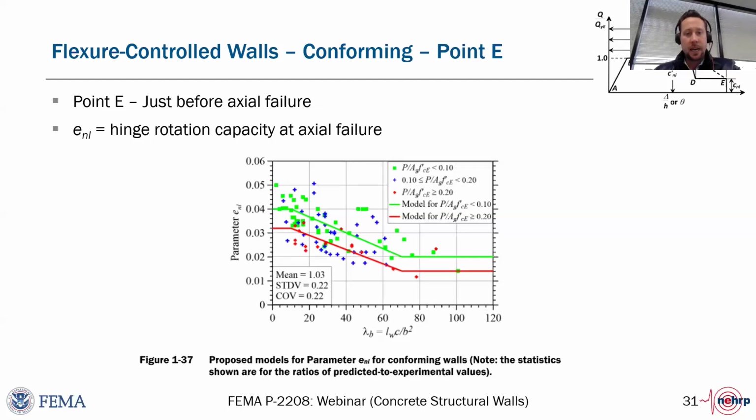So then we get to the actual modeling recommendations. And one of the really interesting things that came out of that database analysis that Saman and team had done was that in the past, the table was basically dependent on shear demand ratio, shear stress basically in your wall, and axial load.